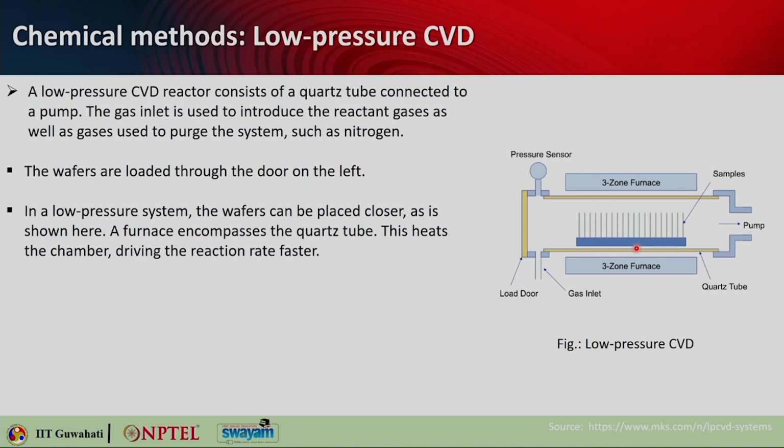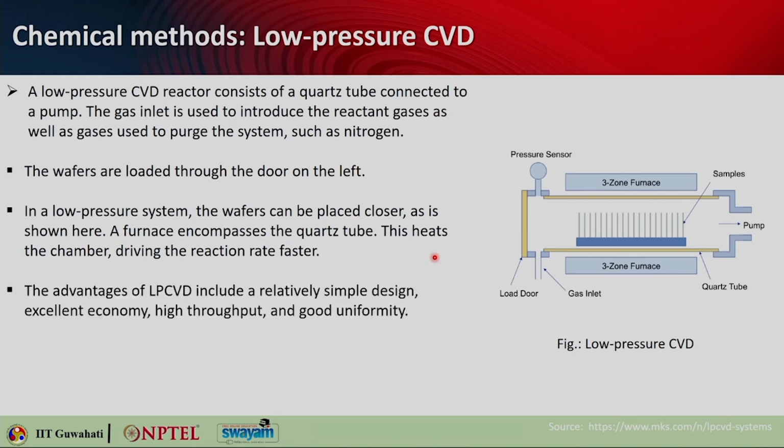In a low pressure system, the wafers can be placed closer, as you can see here. There is a 3-zone furnace that is there from the 3 sides, top, back and bottom, and this encompasses the quartz tube, and heats up the chamber, which drives the reaction rate faster.